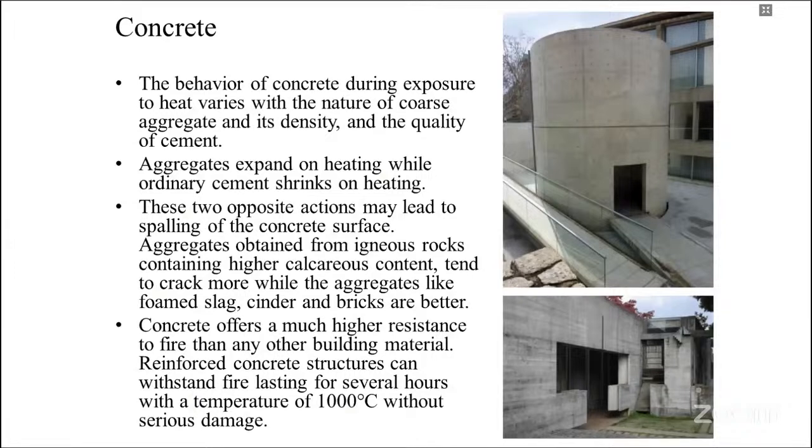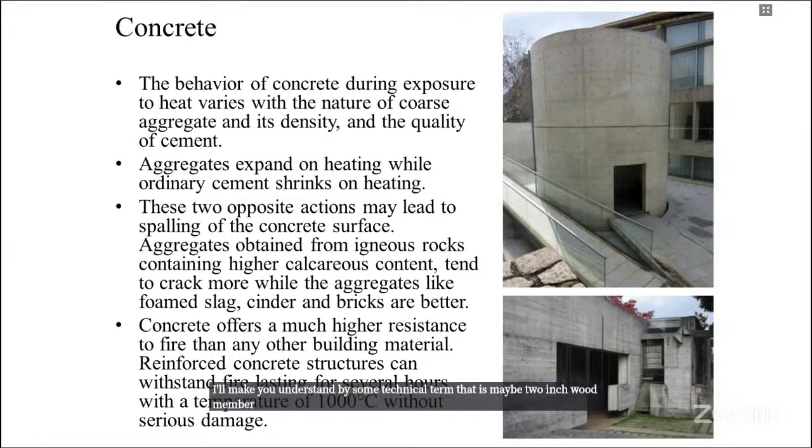Okay, let me tell you one more thing about fire ratings for wood. As we were discussing the rating systems, you might know that there are different ratings. If we talk about unprotected wood, it typically has very low fire resistance. That means, to explain with a technical term, a 2-inch wood member may resist fire for 15 to 30 minutes. So nobody will be using this type of material. This is said to be unprotected wood.